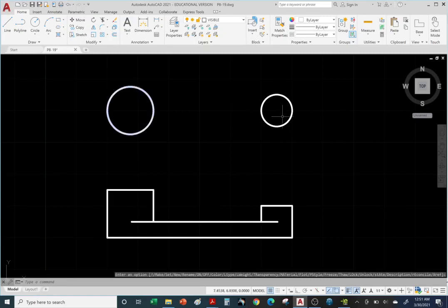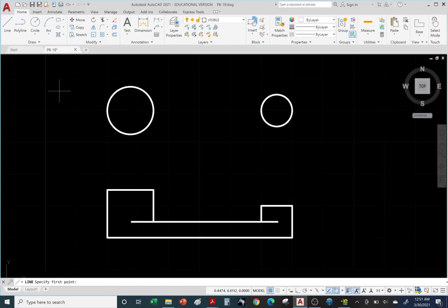Okay, so now we're going to connect the two circles using the line command and TAN, for tangency. Once you click on the line command, type in TAN, enter. Let's do the top portion first. Now we can see the green lantern ring, right? Click. Okay, there it is. You can see it's tangent to the top portion, and then we'll type in TAN again a second time, enter. As long as you hover anywhere on the top half, it'll automatically make a tangent. Click. There it is. See how it made a tangent, and right click enter.